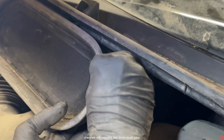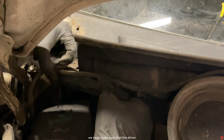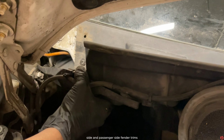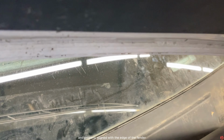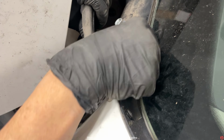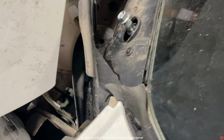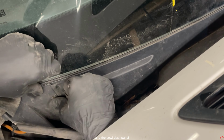Then, we will reinstall the 3 push pins to secure the cowl panel to the cowl dash panel. We must make sure that the driver side and passenger side fender trims are placed in position and properly aligned with the edge of the fender. Then, we will reinstall the 4 push pins to secure the 2 fender trims on cowl panel and the cowl dash panel.